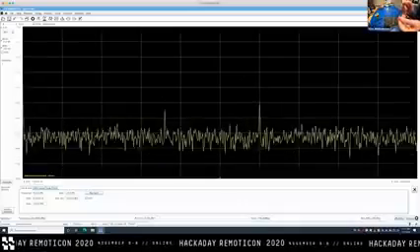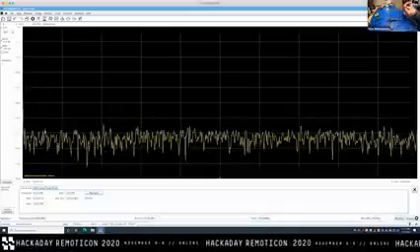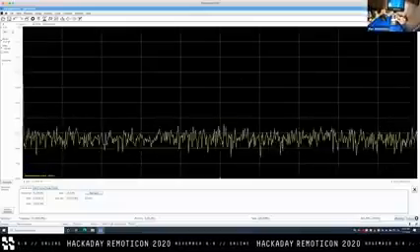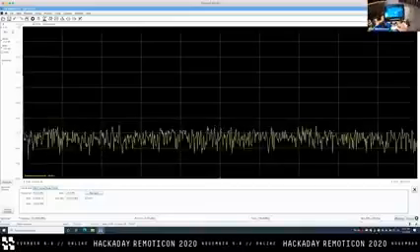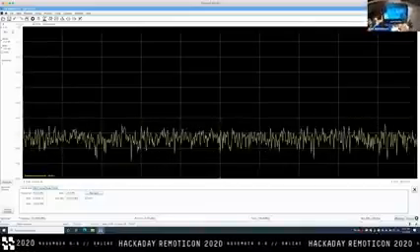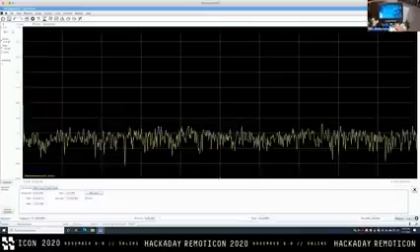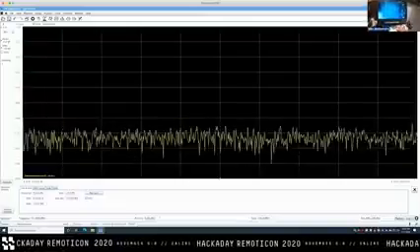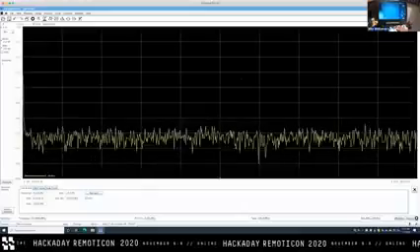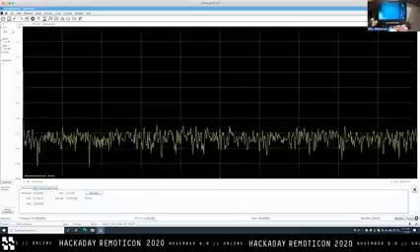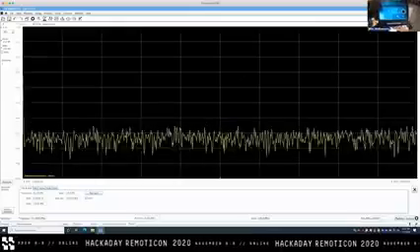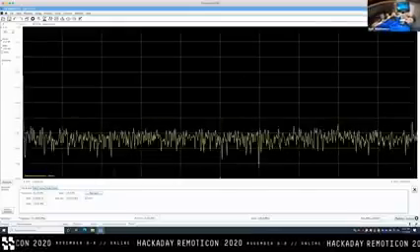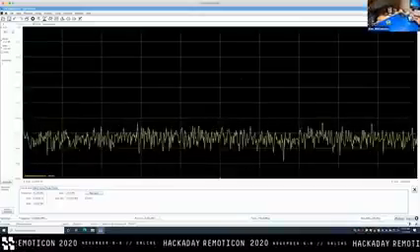if we get close to this thing that looks suspiciously like an oscillator. So just for giggles, I'm going to throw this all under the microscope and have a look at what we're actually looking at. And especially if you're debugging your own design, it should immediately be apparent what you're looking at because you'll know. But lo and behold, this is an FTDI FT232H serial converter chip. If we look up here in this corner, that thing that looks like an oscillator is indeed a 12 megahertz oscillator. So it sure looks like we're picking up 12 megahertz and a couple of harmonics of it.